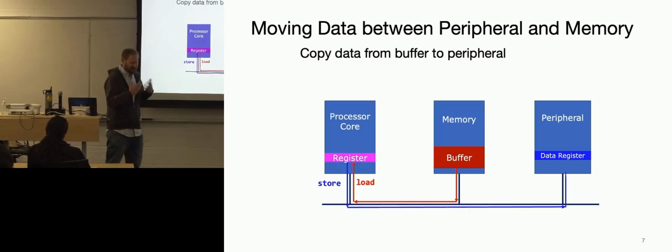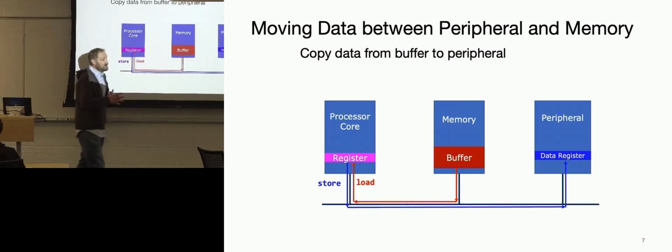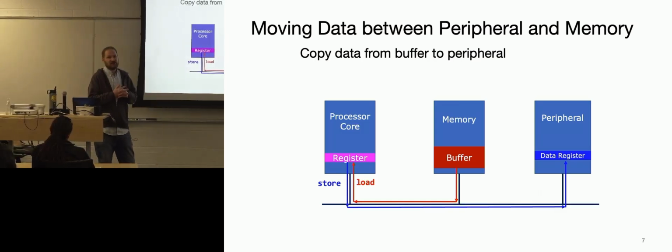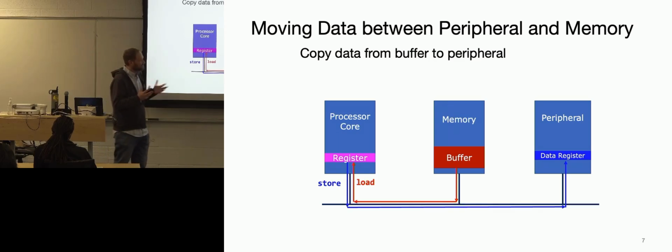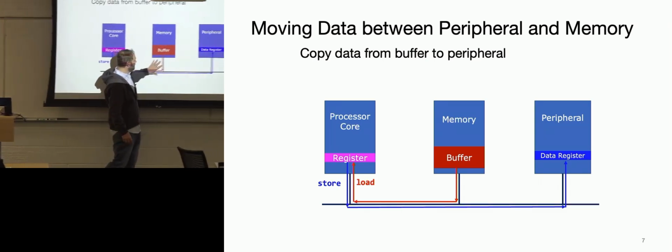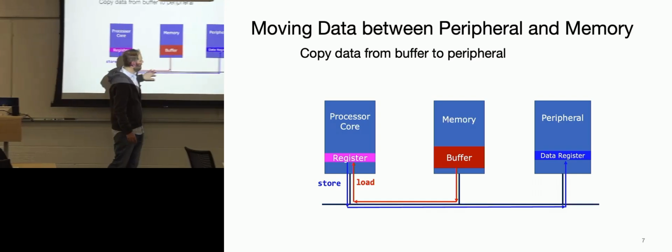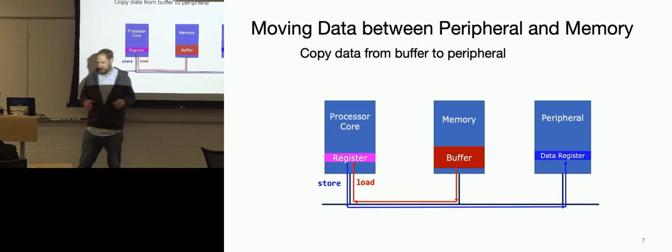If you're doing sound generation and you want to play a sound through a DAC, there's a nice website that will take an MP3 or WAV file and turn it into a C array that will just play that sound for you. So all that's done for you, which is nice, and you can play actually pretty good sound, maybe 5-10 seconds. You could do that by taking it out of memory and processing it through the core. It's just that this blocks your core from doing anything, and it fills up your bus. Not in a bad way necessarily, but it certainly holds down your core.